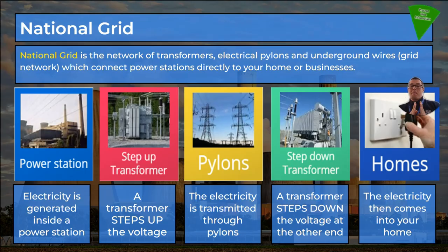They do that by massively increasing the voltage as the energy is being transferred, and in doing that, by keeping the power the same and increasing the voltage, you massively reduce current. Reducing current means that there's less heating, there is less energy wasted. That is a good thing.